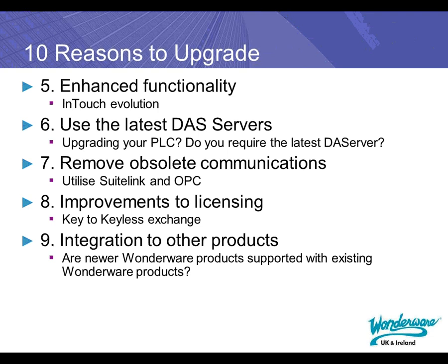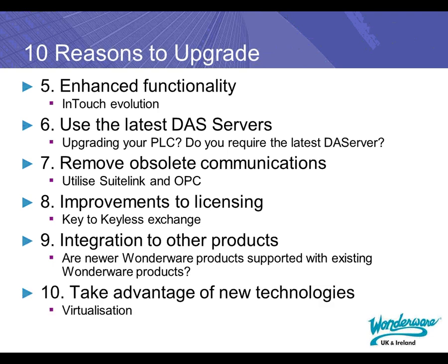It cannot be guaranteed that later Wonderware systems on part of a plant will integrate with existing Wonderware products. For example, if you move to Historian version 10, that cannot actually import tags from a version 7 InTouch application. And take advantage of the new technologies. As mentioned previously, later versions of InTouch are supported in virtual environments.